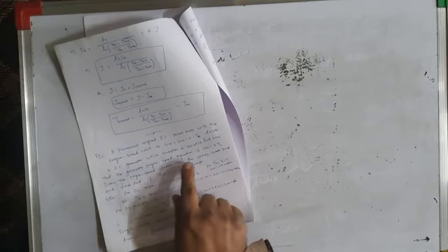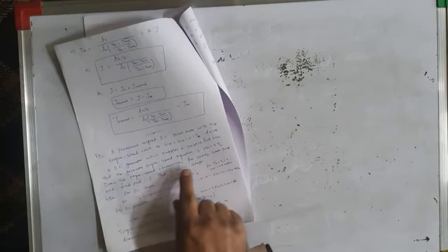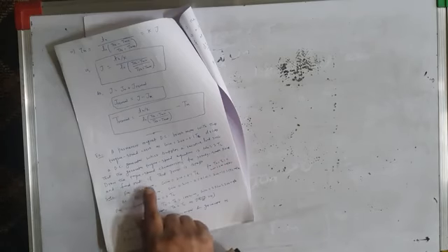So this is the numerical problem for you. I will read it. It's written here that a permanent magnet DC brush motor with the torque speed curve omega m equal to 200 minus 0.1 Te drives a DC generator which supplies a resistive load such that the generator torque speed equation is omega m equal to 2 TL. Draw the torque speed characteristics for the steady state point and find out if that point is stable. I will give you this written problem on WhatsApp.